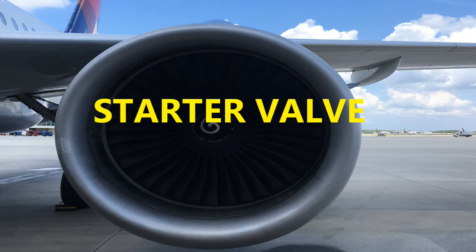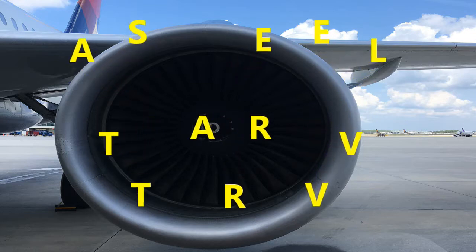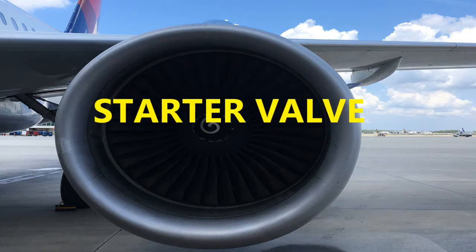Where is the start valve located? By the way, that's a test question. You may want to write that down in your notebook. It's actually at the 3 o'clock position on the fan frame. And of course, it can't be far from the starter, so it is actually above the starter, at the 3 o'clock position. Keep that in mind. Its normal position, should it be open or closed? It's going to be in a closed position at its beginning, before the start sequence begins.